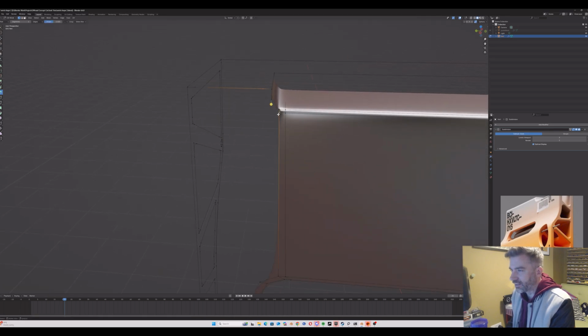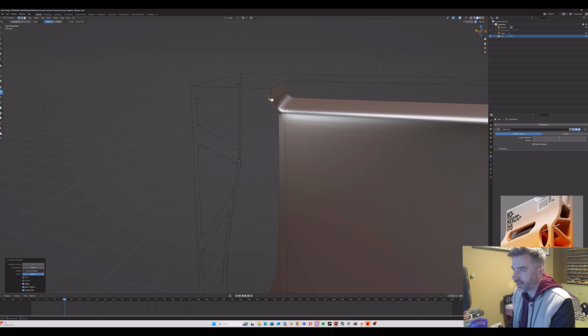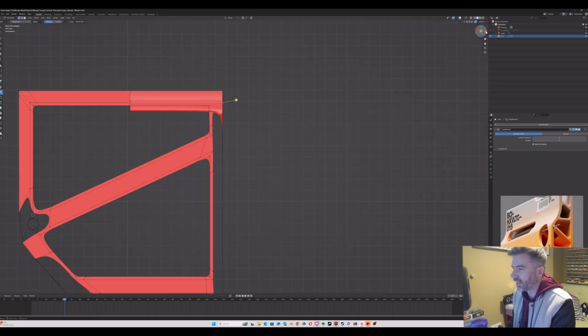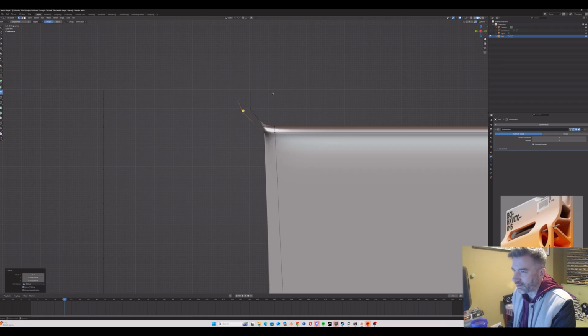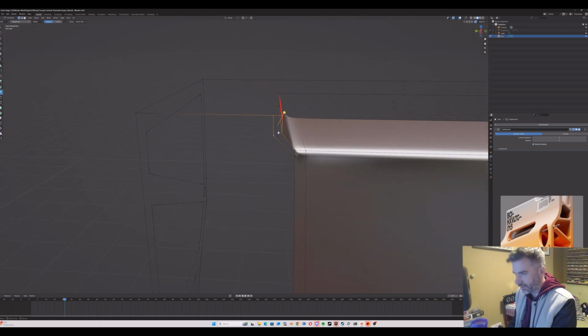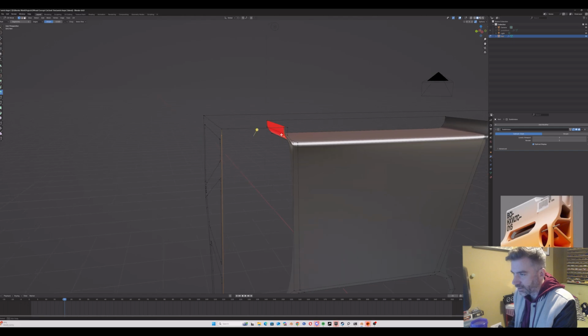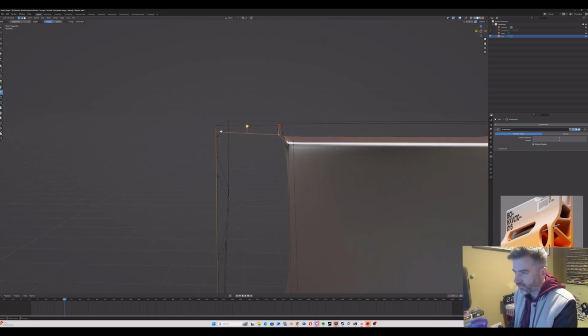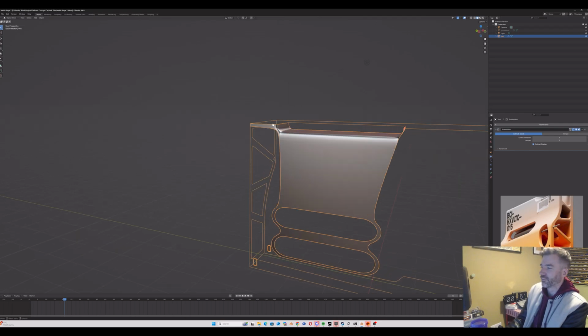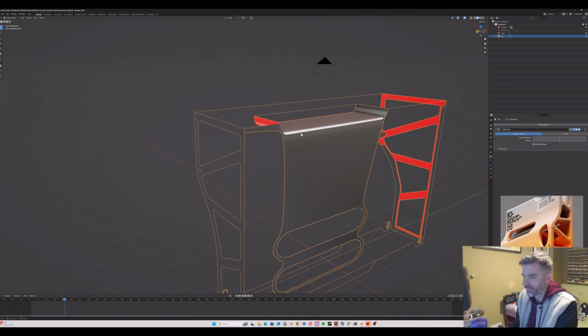And what we can actually do is hit the F key between these two and then put another vertex in there. And I'm just going to make sure I'm working entirely on that view. Again, it doesn't have to be super tight here, but now we can connect these faces and we'll just make sure we've got the right ones. So you can see we've got a nice tight edge along there. And we could actually connect this up. Can't put a whole polygon in there yet, but if I put another cut in there, and again we might end up deleting these, we will just find out. But let's put this in. We've got a face the wrong way, so we're going to select both of those, recalculate. You've got some lovely, smooth, soft geometry there, exactly what we want.